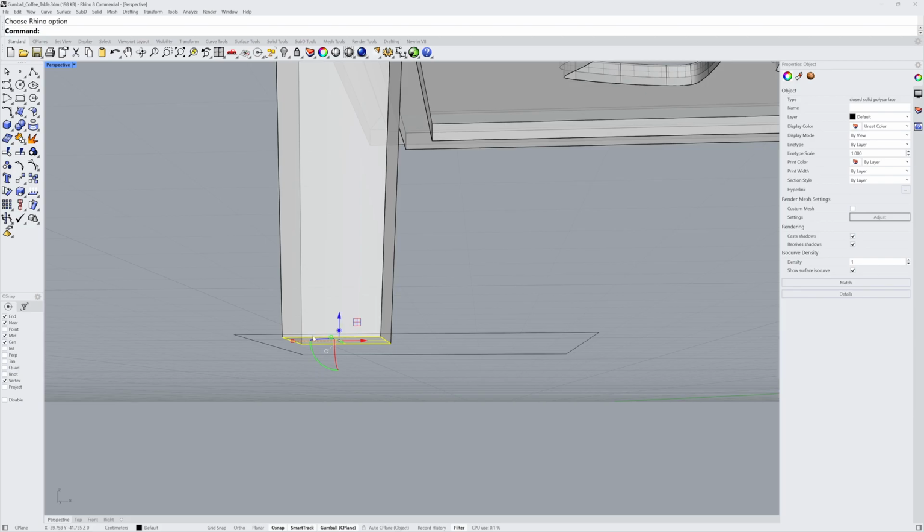I want to construct a foot at the bottom of the leg that matches the taper that we arbitrarily assigned by scaling. In order to do this, we'll have to use the Extend Face feature, which is new on the Extrude handle in Rhino 8. First, let's move this subobject up in the Z-axis by clicking and releasing. I'll type 1 for 1 centimeter and press Enter.